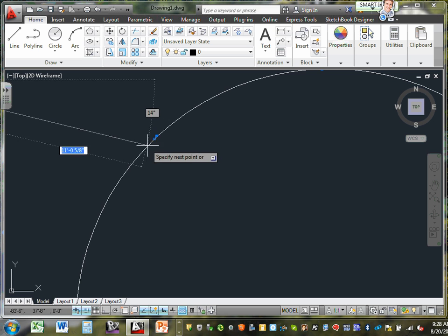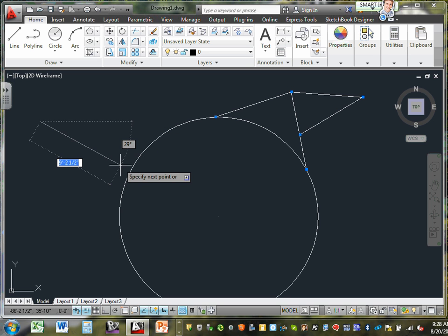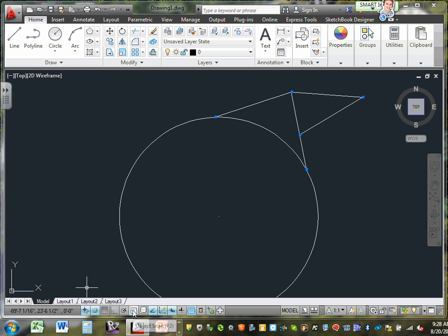If you guys turn the snap off, can you see it doesn't touch? It doesn't tell you if you snap it off. That happens, Karen, when you're trying to grab your receptacle and I bring the red line for me, and your receptacle is slightly not attached to the wall. You need to go turn your snap on and move it. Snap object or object snap.